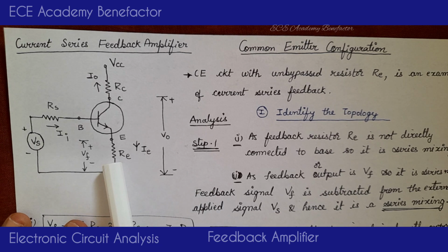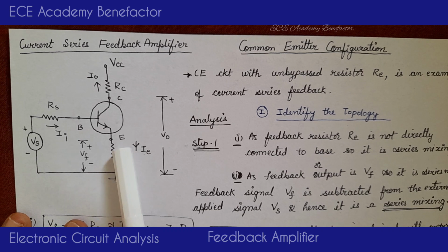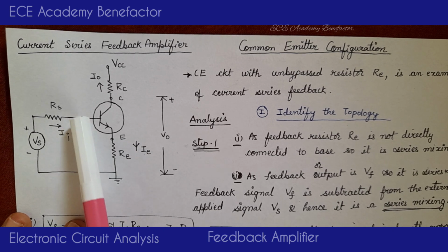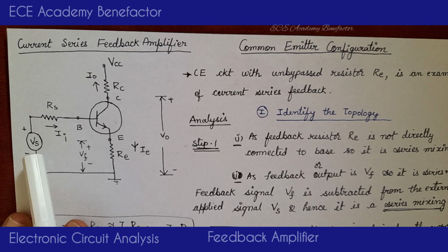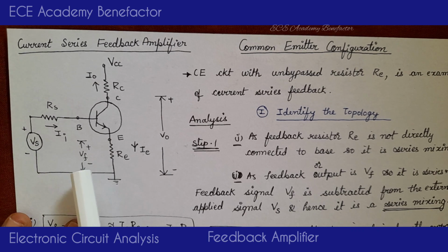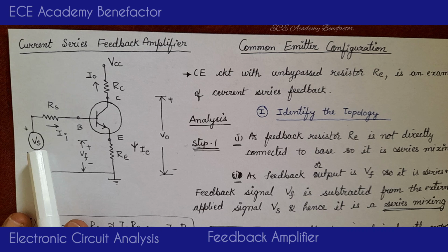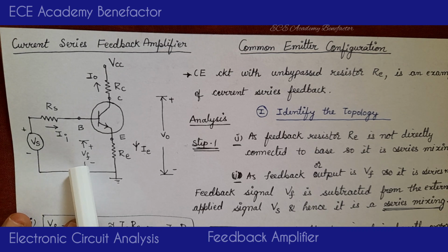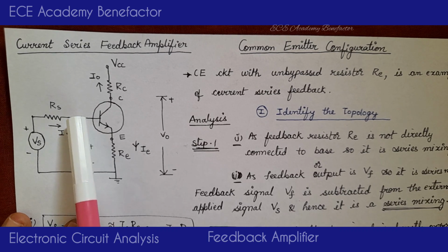Or the other way of telling it is series mixing is, just by visualizing, as the feedback resistor RE is not directly connected to the base of the transistor, it is series mixing. Or, as the feedback signal subtracted from the externally applied input signal is voltage, it is series mixing. The feedback signal is VF and the externally applied signal is VS. So this is a series mixing. Or you can easily say this is series because it's not directly connected to the base.